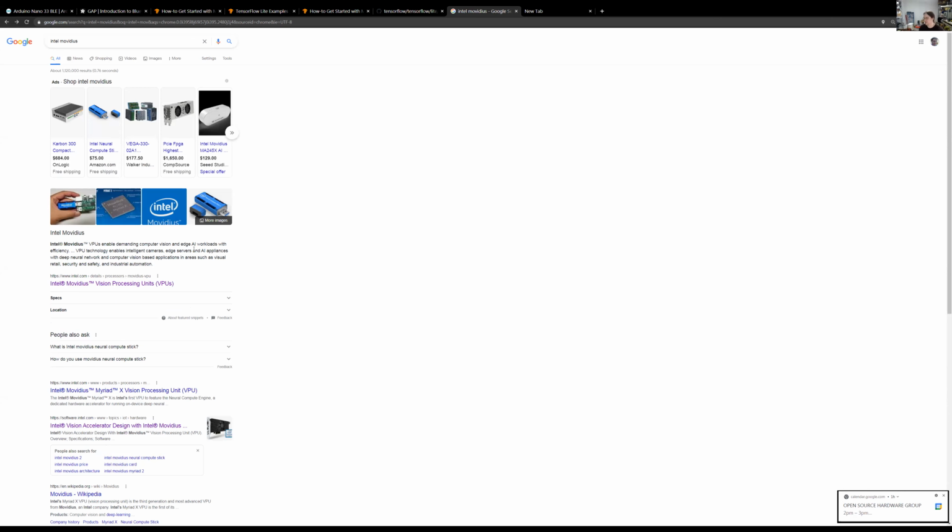There is the option of generalizing the last output nodes and then running those output nodes on a general purpose processor like the nRF52 or another ARM-based processor. But there's not a way of doing real-time learning or model learning on the device, not quickly at least. The reason being is that it takes maybe about a second or two for the new model to get loaded into the chip.